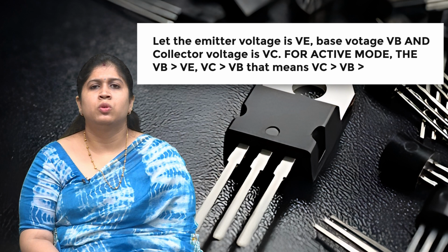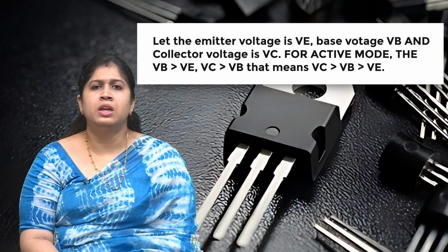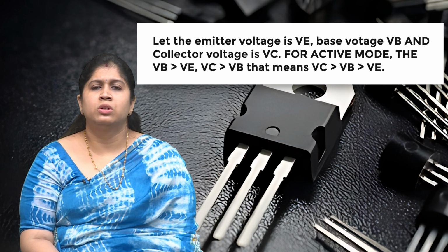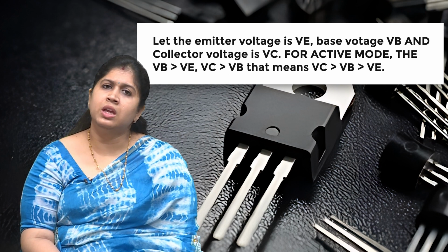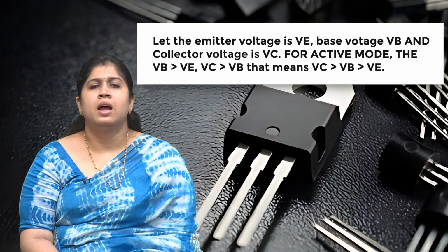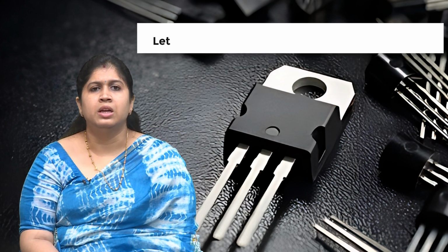Let the emitter voltage be VE, the base voltage VB and the collector voltage VC. For active mode, VB is greater than VE and VC is greater than VE. That means VC is greater than VB and greater than VE.